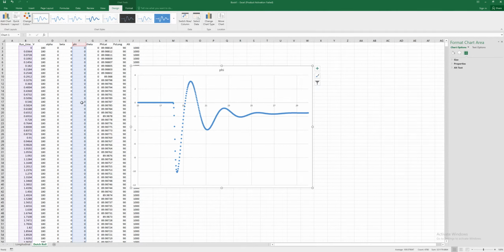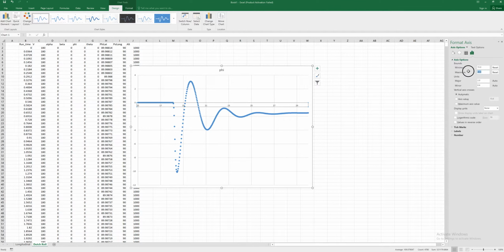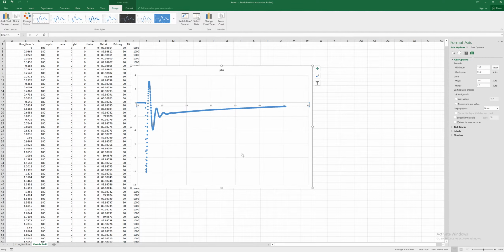Can also look at the bank angle. So this is phi, and again, the phi is going to pick up that Dutch roll mode. And let's zoom this back out. So we're looking at all of that data, and so phi started off really sensitive to showing us the Dutch roll mode. But then this portion of phi actually shows us the spiral mode. You can see that the spiral mode is convergent, and it's returning to a zero bank angle, right? So as time goes on, this is asymptotically approaching that zero bank angle.